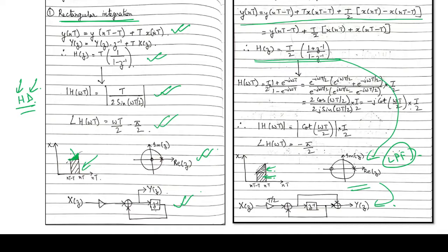Now you would say, how can both be true at the same time, right? The thing is that a low pass filter is an integrator in the roll-off region. When we talk about the low pass filter, it is something like this. So this is the roll-off area. After the cutoff region FL, in the region of the straight line, your low pass filter will act as an integrator.